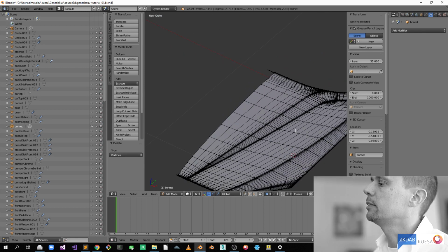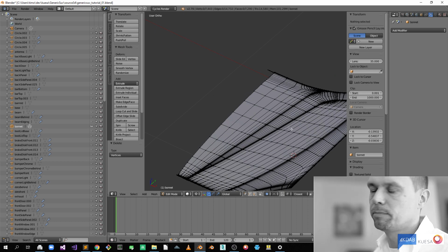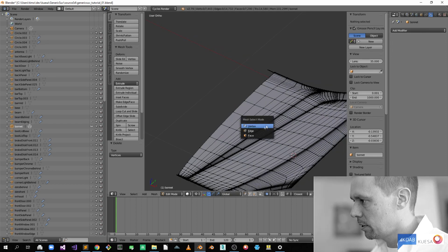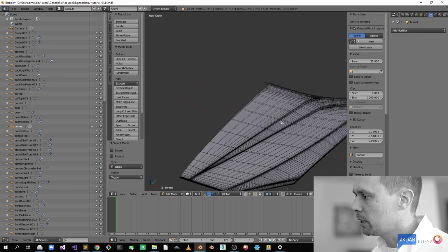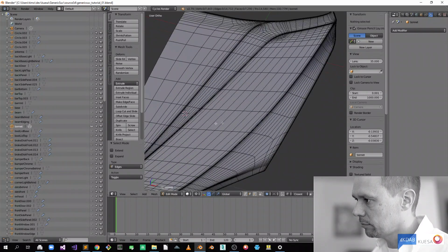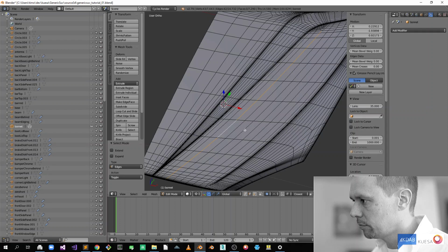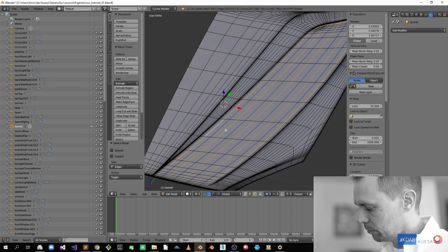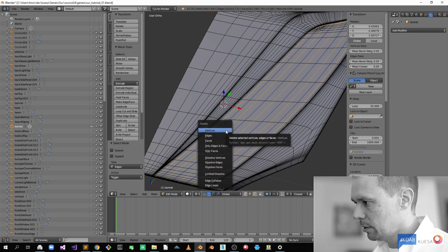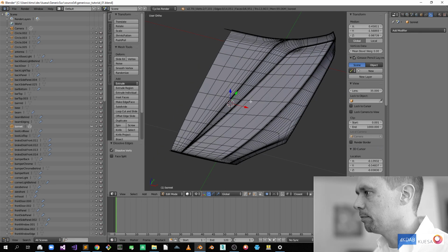And now let's reduce the mesh resolution where we don't need it. So we are going to use the same technique as before. We go to the edge mode and select some edge loops we don't need. And we can dissolve the edges, so the faces are persisting.